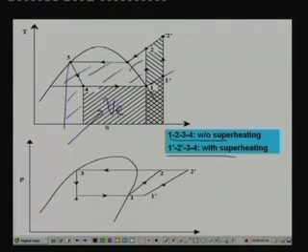Okay. So, this is QE and this is your work of compression without superheating. Now, let us say that I have superheated it. Superheated means what I am doing? I am pushing this exit condition from the saturated vapor to a superheated vapor, along the constant pressure line. That means, this is the constant PE line. So, it is a sensible heat transfer process, assuming that there are no pressure drops, so it is taking place isobarically. So, this point is shifting to superheated region.